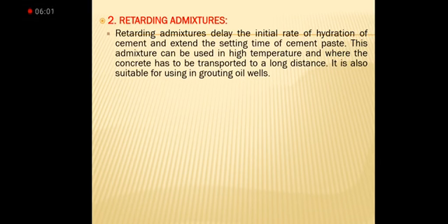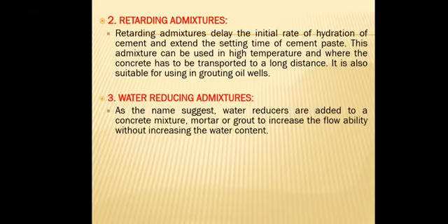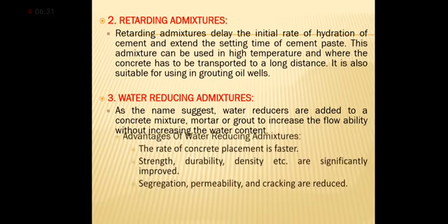At that time, we put some retarder admixture so that it will not set soon till it reaches the destination. Next, water reducing admixture. Here, water reducing means we don't want to provide extra amount of water, but we want the concrete to be a little flowy. That is water reducing admixture. It is added to a concrete mixture or mortar grout to increase the flowability without increasing the water content.